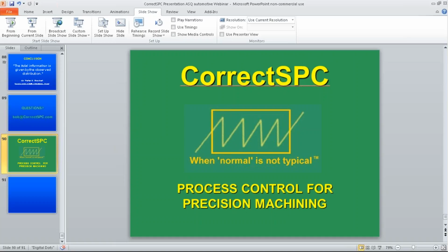Okay, here's some more on over control is adding variation, not minimizing it, correct? That's what you were saying. Well, it does, because especially what happens with over control in machining, that means that the operator is messing with the machine more than they need to be. In fact, when I've implemented this, I've actually reduced the number of operator interventions. Sometimes they were intervening every 15 minutes, and then we get it down to maybe twice a day because there was no point. So why have the operator intervening in the machine if they don't need to?